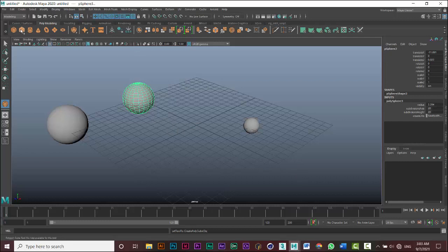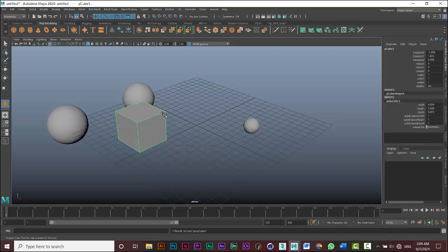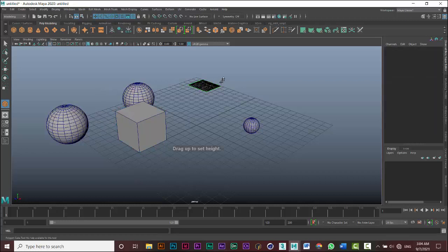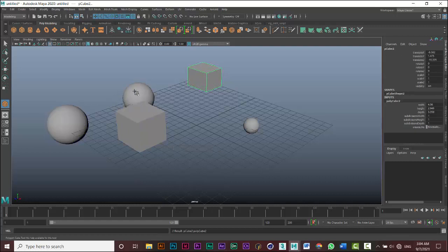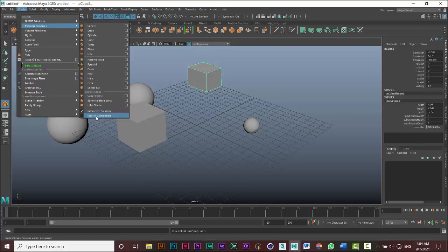If it's a cube I'm trying to create, you see, drag the base on the grid, then pull up for height. So I drag for the base of the grid. Okay, then once I leave, I drag once again for the height. All right, good. So now you can see it's still in the creation mode. That means if I drag again, I'll be creating another cube, just like it was with the sphere. And that's because I had the exit on completion unchecked.